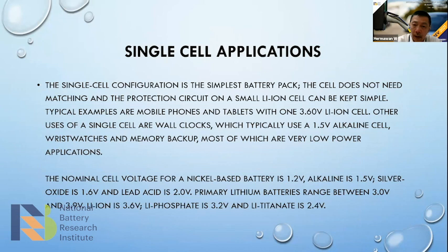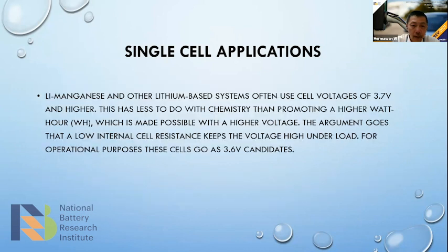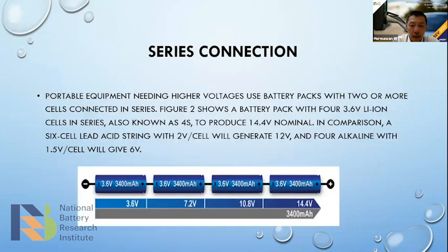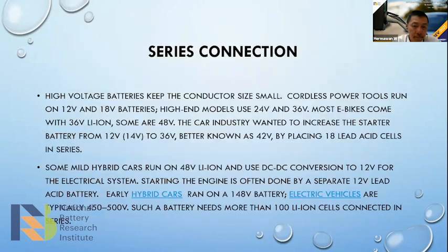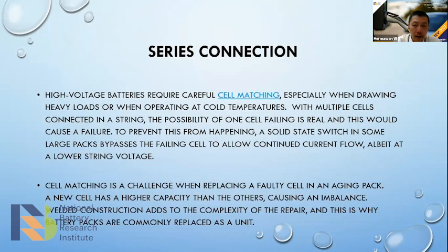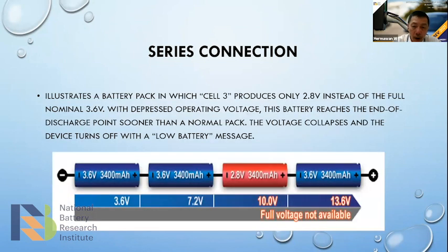a small single battery sometimes gives us some protection electronics. There are so many kinds, and then we can see how the series connection works in the battery. If we have 4 batteries, we can see 3.6 up to 14.4 volts, but the ampere hour is still the same. A connection like this, actually in the fleet, this series connection will make a higher voltage.